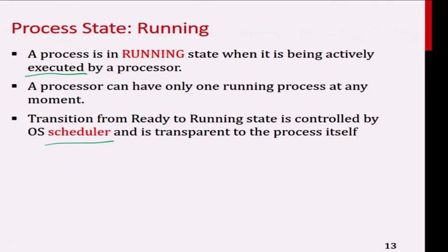That's why I said the programmer mindset must switch such that every task is a mini program by itself. I must put in the necessary logic and the safeguard to ensure that this task that I write will run when the data is available. And if it's supposed to synchronize with some other task, I also need to put that in my code. You do not explicitly call a task to run. That is the job of the OS.